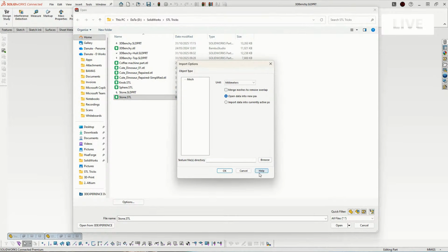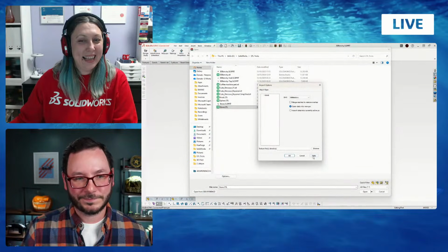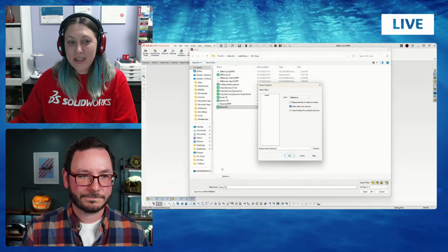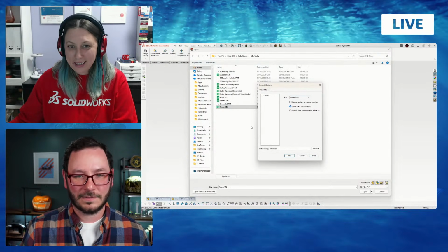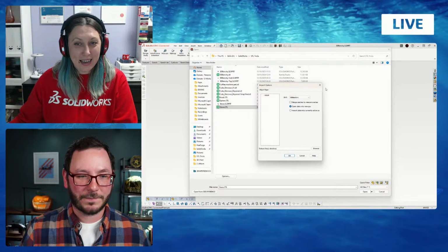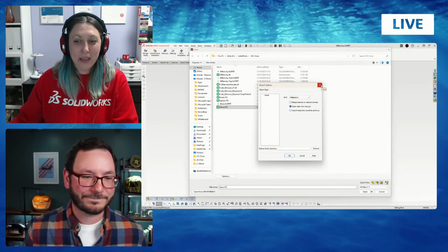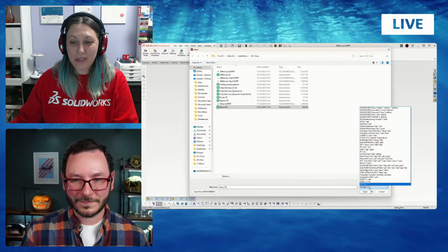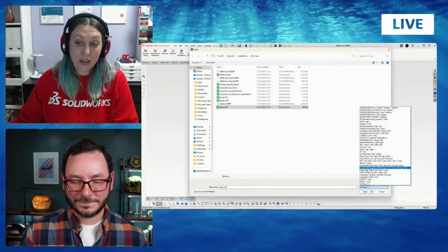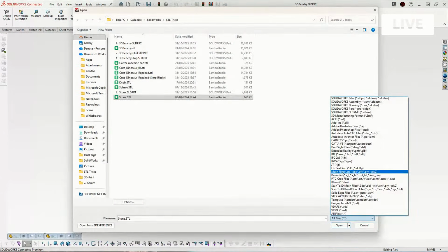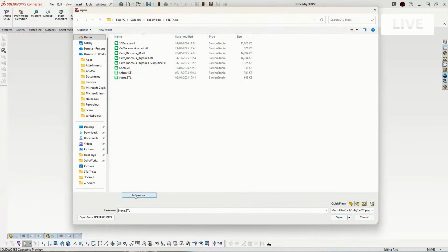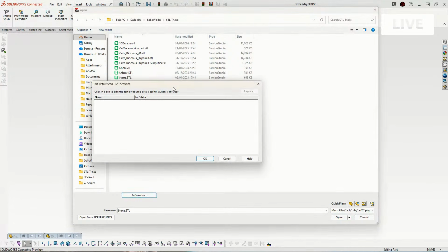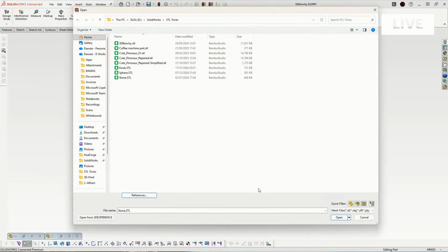Where you were showing it before, that's your defaults, right? This you can do kind of file by file. Yeah, but are you seeing now that if I hit options now, it's not the same dialog? Right. Yep. Okay. Yeah, that's the other mistake, and this will get people confused. You have to choose that you would like to import actually STL. That's another great tip. And then here, options sometimes is missing. That's the other problem.